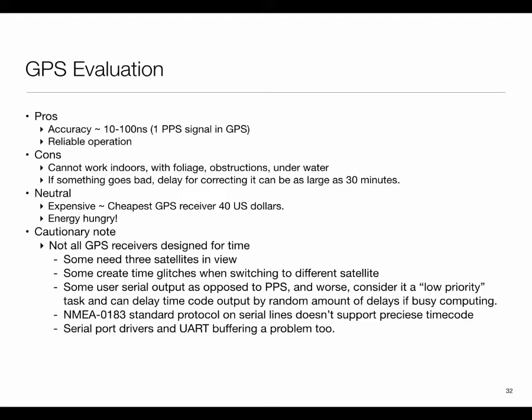And of course, correspondingly, the time is also accordingly accurate. So anyway, that's the nutshell of why GPS is great for timing. And again, consumer grade GPSs, you can buy boards from SparkFun or Adafruit. They can get you to, let's say, a small number of tenths of nanoseconds once you have the satellites locked in. Otherwise, it takes time. You cannot just power it down, pick it up, and say, hey, tell me the time to 50 nanosecond accuracy. It can't.